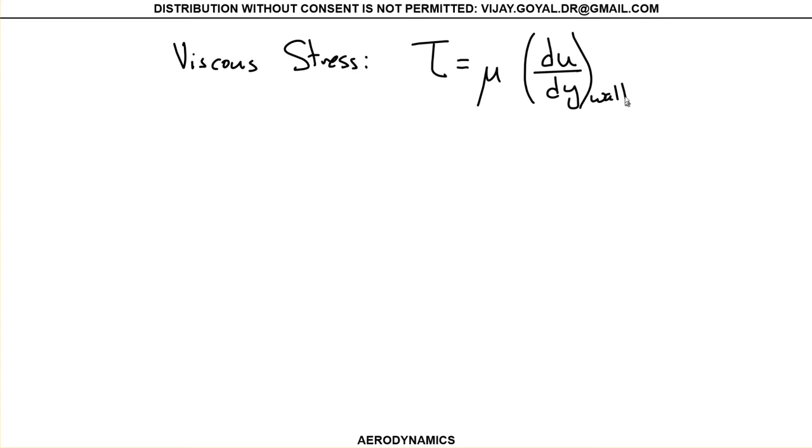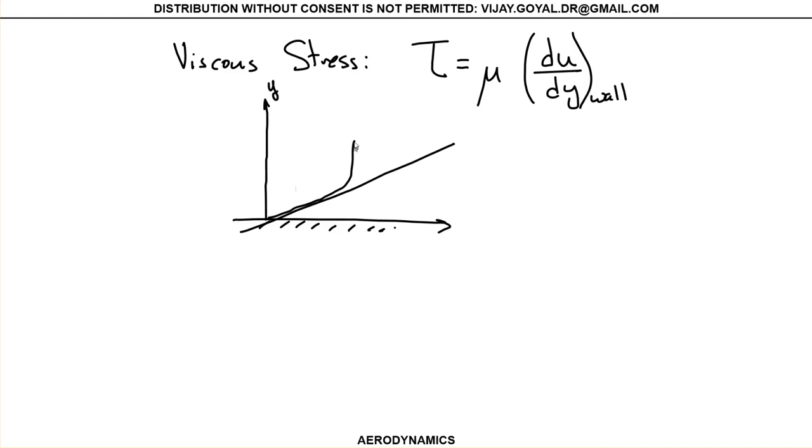The stress, the viscous stress, at the boundary layer. So I'm saying I got the boundary layer, I got the wall, this is your wall, okay? And your stream is measured in delta. Now you're going to have a slope that goes right there, and it's going to do something like this. Okay? So what we are saying is this slope that takes place here is du dy, and you can immediately see that the slope is going to determine the size also of my delta.